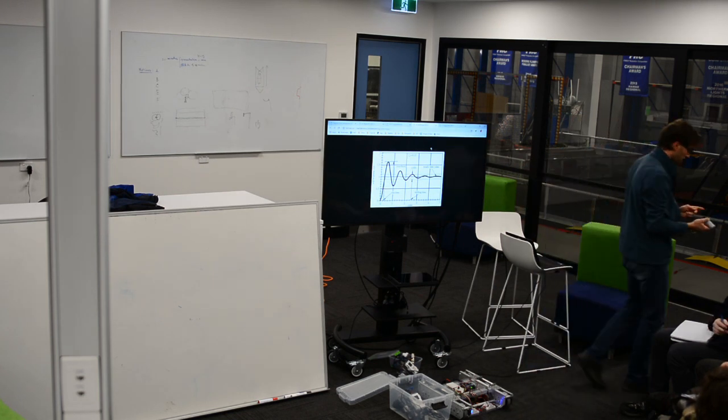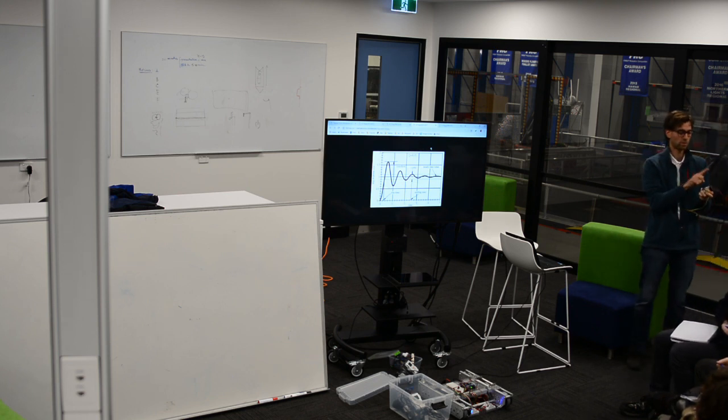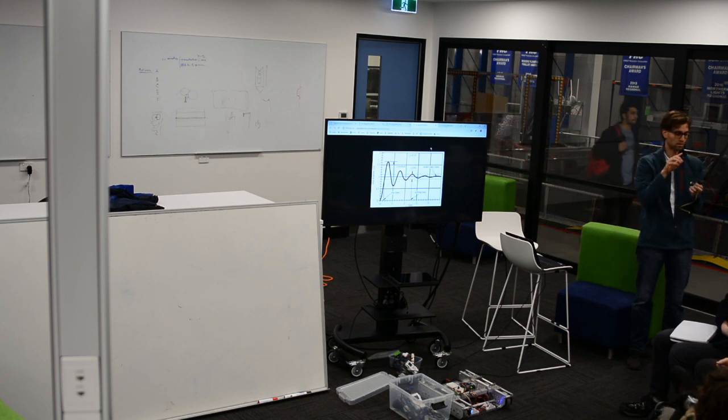That's the motors. You've seen them on the robot, whether you've seen them off or not. On the back of that, you've got the power, the red and the black, which is what makes it go. Then you've got a connector like this that goes in the back, and this talks to the encoder. Underneath this black cap, there's a magnet that spins around and some magnetic sensors. The magnetic sensors generate a square pulse when the shaft spins. And there's two of them.